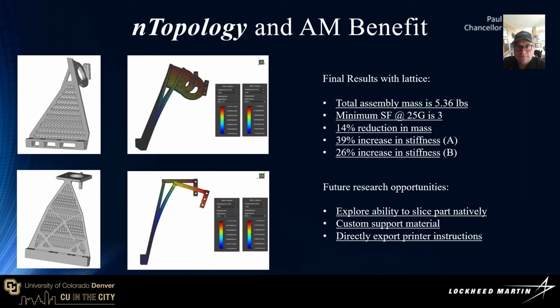In this slide, you see some of the interesting additive manufacturing design features Topology brings to the design process. Lattice infill has been added to the rocket mounts. We found that these lattice additions add very minimal mass but bring a nice increase in stiffness response. The stiffness increase brings better modal responses and an overall increase in safety factor. With more time, we were hoping to physically print and test several components using these technology features.